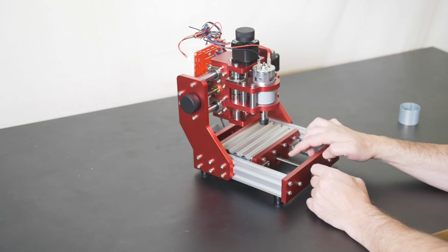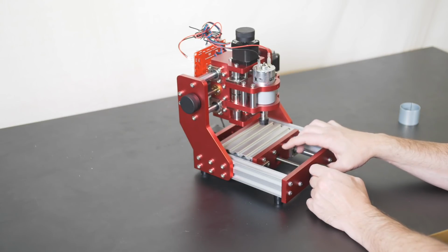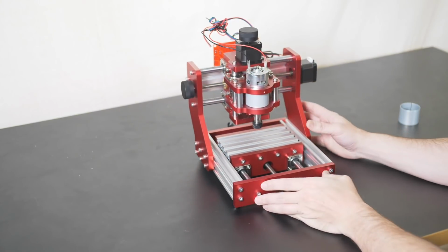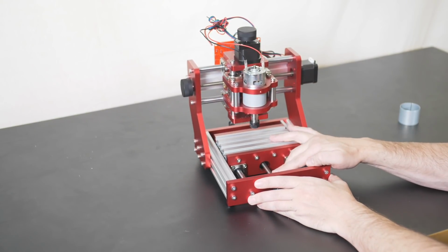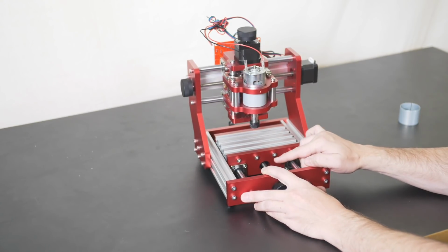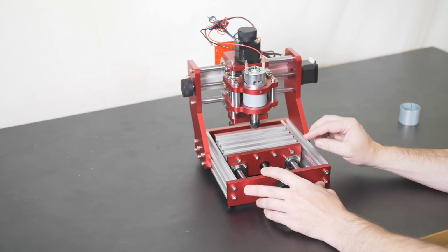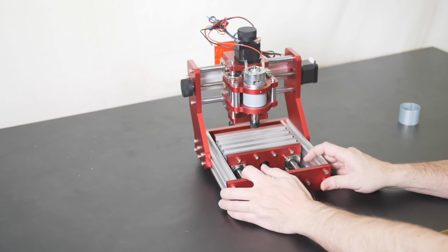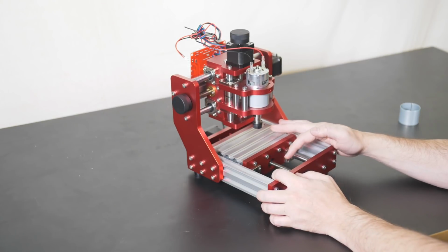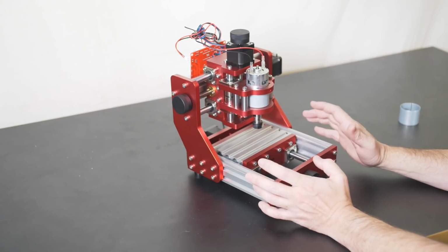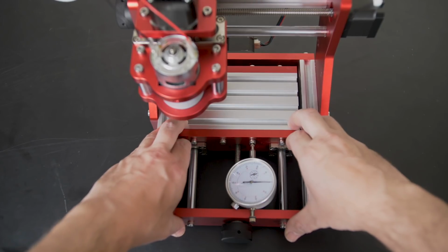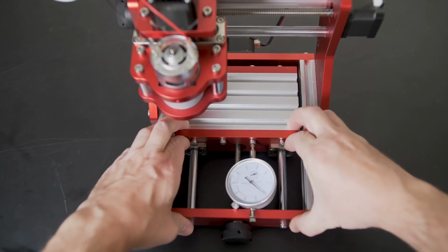Now the next problem I have is a little bit more serious. It involves the anti-backlash nut on the lead screw. So if this was a more expensive CNC machine, we would see a ball screw here instead of just a regular old lead screw. And ball screws have lower lash, or also called backlash, but lash is just the term there. And so yeah, the anti-backlash nut does help, but if you don't install the anti-backlash nut correctly, this problem happens with the bed, where you get a bit of play in the bed.